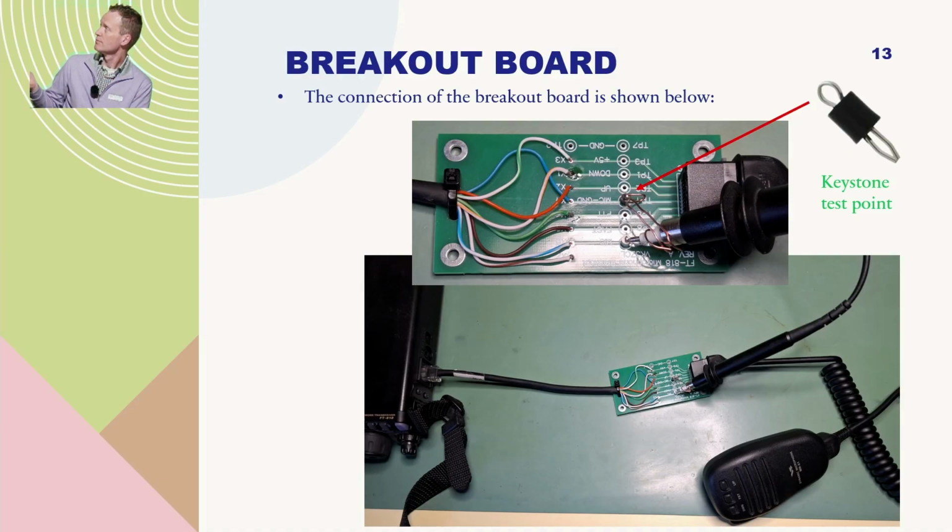So I had a short tip, and then I also had a bit of wire here wrapped around the ground part of the probe. And the reason I haven't used a big long clip lead here, which is often connected to the probes, is just because of noise level. I'm trying to measure very small signals, so I want to keep this loop really small, very short connections. And that worked pretty well.